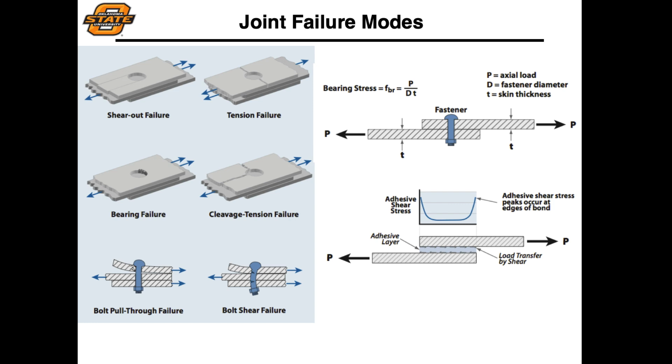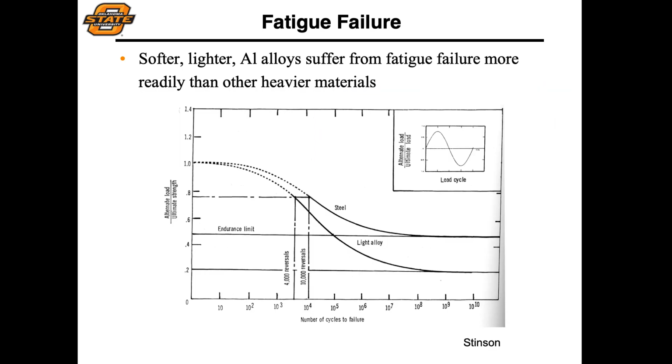Whenever you're putting a hole in a material, you're obviously going to have stress concentrations located near these holes in your material, as well as a greater propensity to have critical material deficiencies or defects within these particular areas. So you might have a crack, and that crack would then propagate under that stress concentration, and then that might result in a failure.